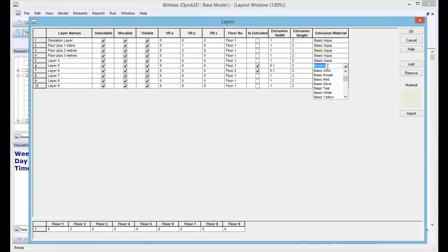Here we have a brick pattern, a repeating pattern, but equally well you could just pick a colour, or you could pick a more detailed image. You could have lots of paintings or full pictures included on the walls using this method. It's also possible to import different pictures from a JPEG format, and we'll have a look at that a little bit later in this tutorial.